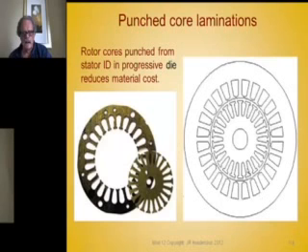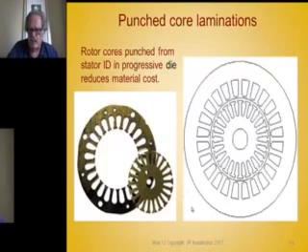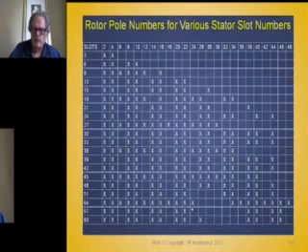And the sides of the teeth should have tapers on them. There can be a radius right there, that's okay. But the sides of the teeth should have taper. The length of the tooth tip that extends past the side of the tooth, in other words the distance from here to here, should equal that distance there, to avoid saturation. So the tooth tip protrusion should be equal to the throat thickness, or the attachment of the tooth tip to the tooth.